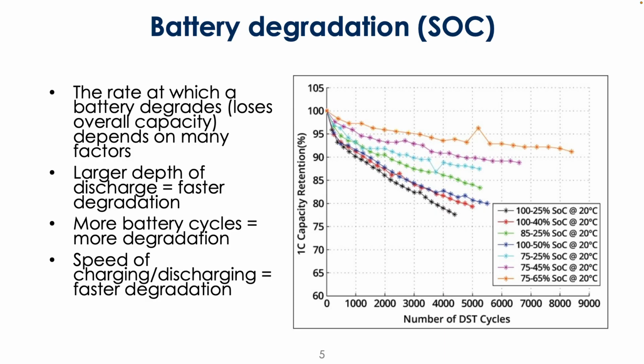So if you were to charge your phone to 90% every day to try and preserve some of the battery, that definitely works and helps, but the relative difference in degradation is not going to be as large because they build in the buffers and because they have good battery management systems. So I would say don't feel obligated to optimize the charging of your consumer electronics on your own.